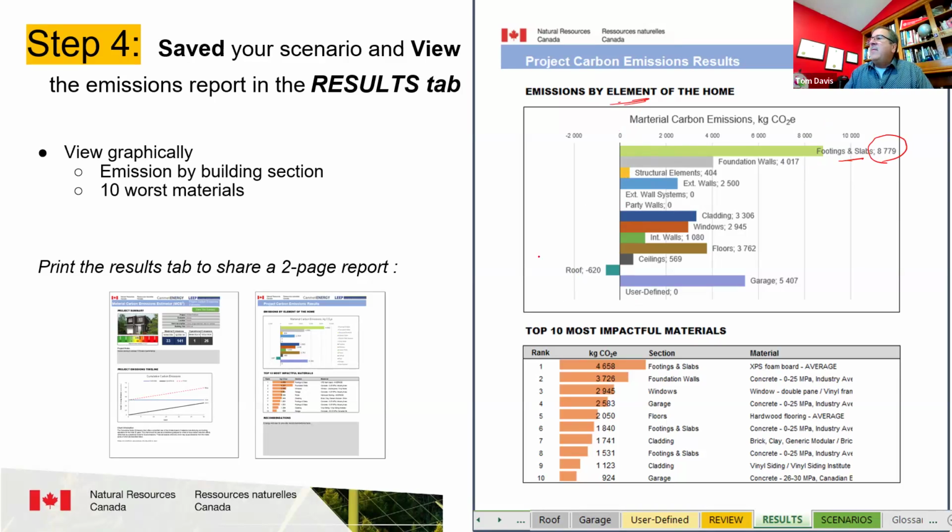If we want to lower the carbon emissions of this entire structure, I would go back and look at the carbon of the concrete mix that we chose. Maybe we can select another concrete mix from the list of opportunities. Again, it gives us the required strength, but might be produced using supplemental cementitious materials, admixtures, which are oftentimes forms of toxic waste like fly ash to take up space in the concrete mix so that we're not using raw materials to do the same function.